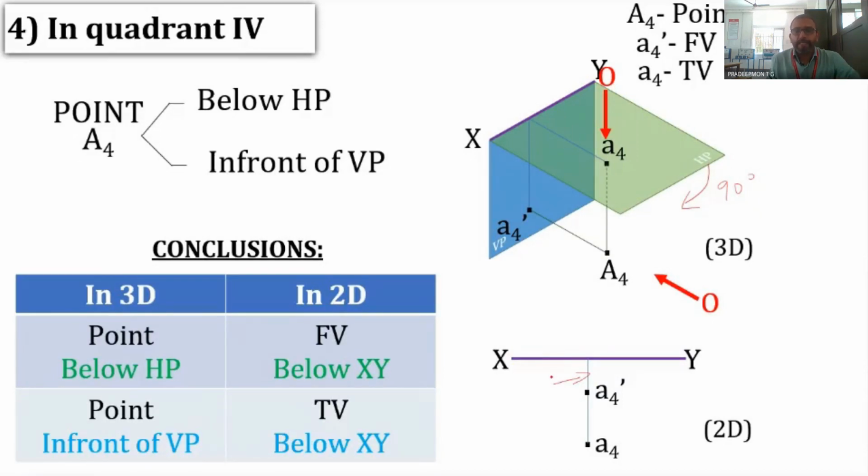Use a pencil in such a way that this line is very thin, and the XY line is dark and a bit thick, not thick enough to measure its width as 2 or 3 millimeters. It should be thick enough, but not very thick. So the XY line should be dark and thick, and the projector line should be very thin and faint.